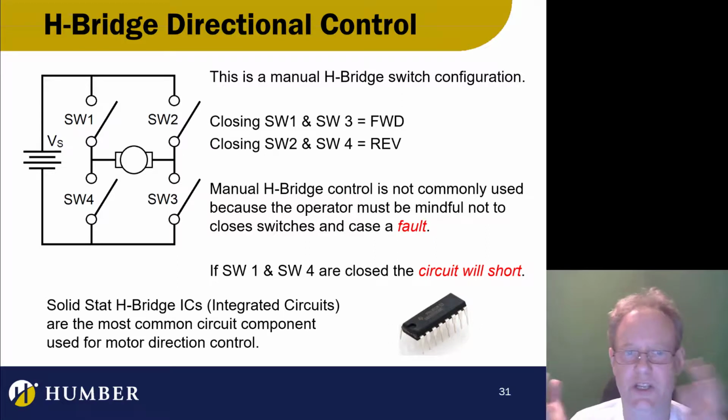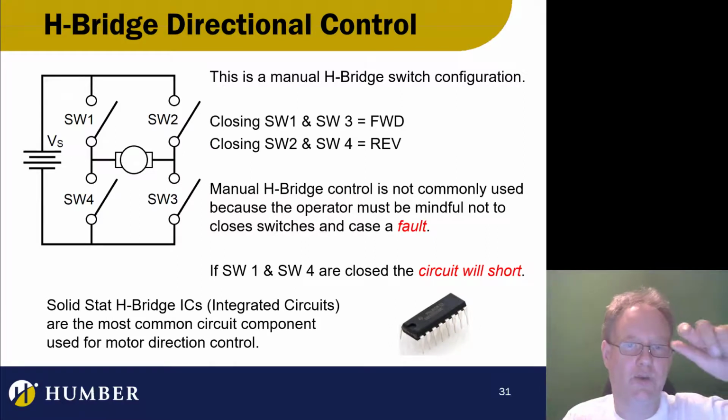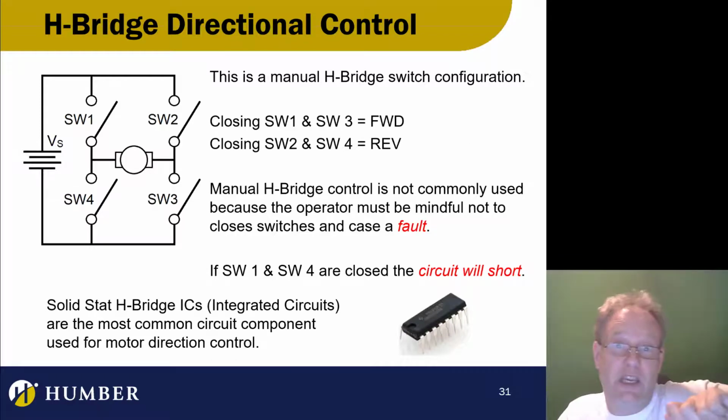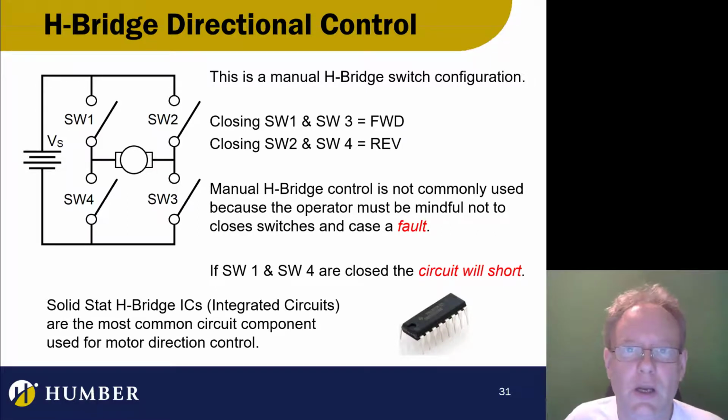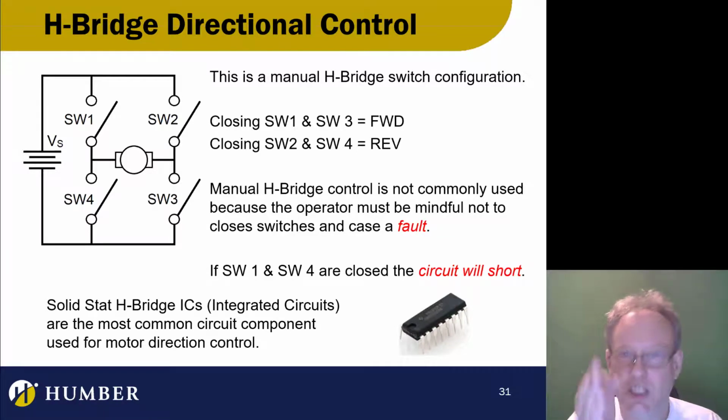Plus, I can switch it really quickly. In this case, I could turn 1 and 3 on, and then I could open them and really quickly change 2 and 4. And the motor's spinning this way, and all of a sudden it's like, well, you want me to spin the other way? Excuse me, I'm driving a load. I'm working really hard, and all of a sudden you've given me direction. Hey, spin the other way. That's not good for a motor. It's not happy about that. You gotta let it stop and chill out for a second before you put it in reverse. I mean, you can't just throw your car in reverse while you're going on the highway.